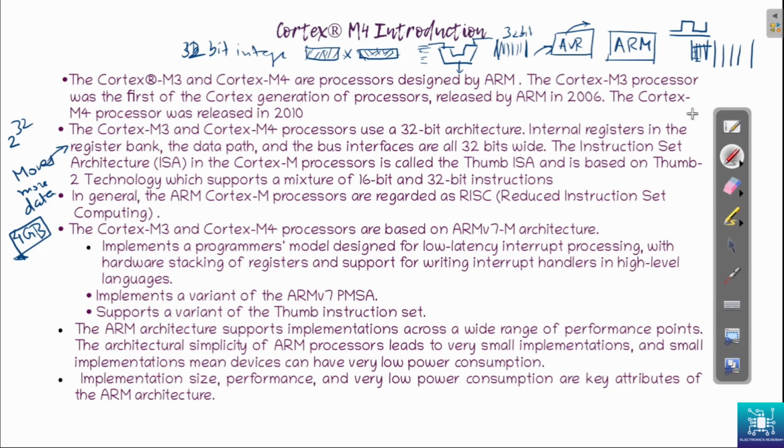The downside of a 32-bit controller to begin with is that it is more power hungry than its 16 or 8-bit counterparts, because obviously 32-bit architecture and a more complex architecture would mean it has more components on the die. So if it has more components, it has more transistors, so obviously it is going to pull a lot more power than its 8-bit and 16-bit counterpart.